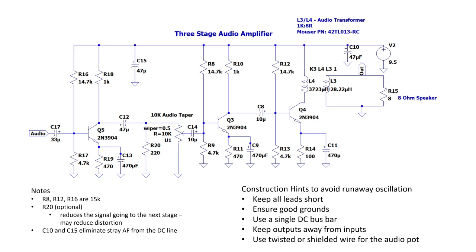Last thing I would say is, because it's 3 stages, we want to build this in stages. And I'm going to recommend that you start with the Q4 stage. You start with the output stage and the speaker, because you can test that and then you'll know that it's working. Then back up and build Q3, then put in the audio taper, then build Q5 to finish it up. And that's the way I'm going to build it, as you'll see in the demonstration.